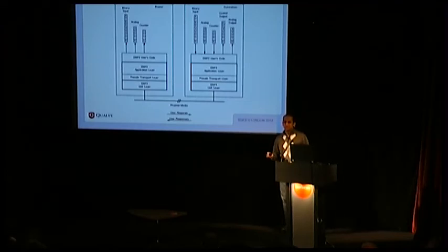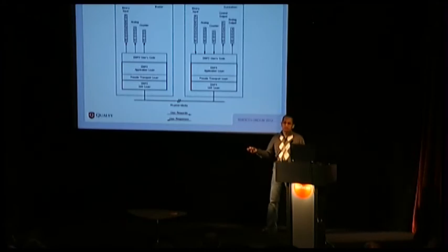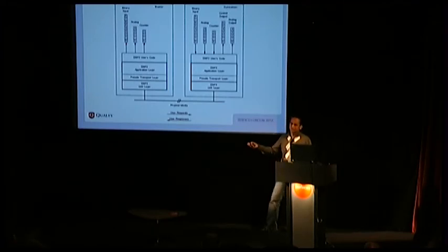For example, Modbus has this constant polling feature where the client, as we saw in our previous example, constantly polls: tell me the temperature, tell me the pressure. You get one response for each request. In DNP3, the server can piggyback all the responses into one. So if you have 5 requests, it can answer with one response, thus saving on network bandwidth.